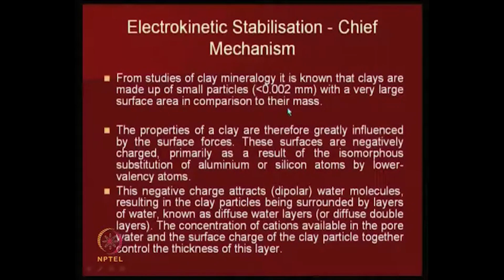I would be trying to describe some more aspects of this electrokinetic stabilization. We know from clay mineralogy that clays are made up of small particles and have large specific surface compared to their mass. The properties of the clay are greatly influenced by the specific area. So, surface forces are higher, and these surfaces are negatively charged primarily as a result of the isomorphous substitution.